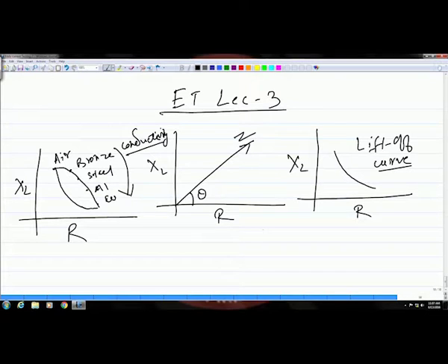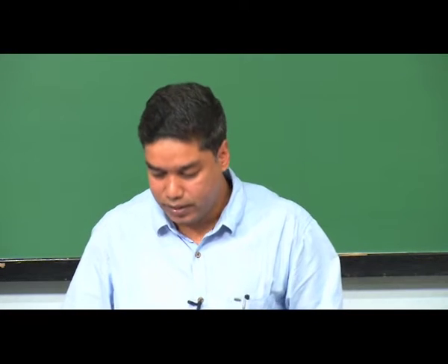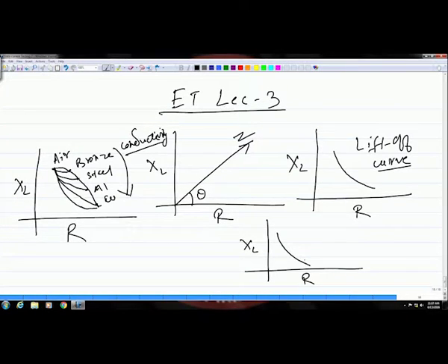And one more thing probably I could tell you here, which is the effect of the frequency of the current which is used in the coil. And one more aspect about this effect of conductivity combined with the frequency is that if you have a sample, let us say I have bronze, and if the frequency is 100 kilohertz, you will see the lift off curve like this.